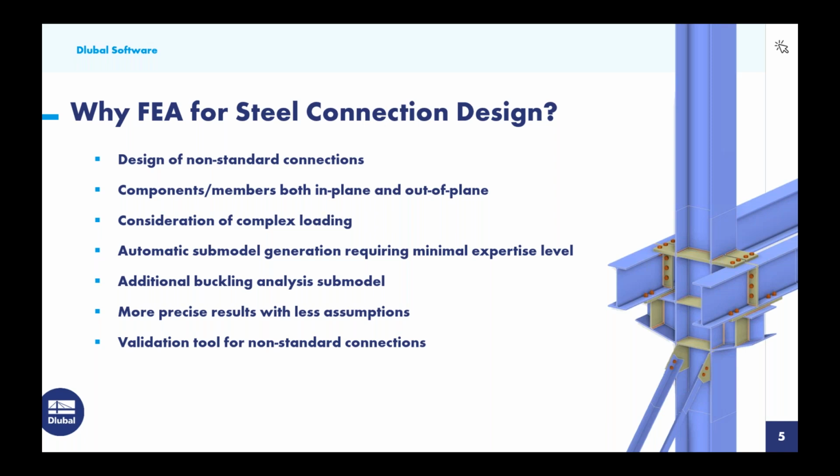They are rather complex, but if you just have a general FEA knowledge, you can go ahead and utilize this capability within the program. We also will perform the AISC design checks of these connections for our bolts, our welds, and our plates, but we will take it a step further to create a second submodel to carry out the buckling analysis. So we'll be able to view the different eigenmodes and failure buckling modes of this connection, as well as the critical load factors. So we'll see that a little bit further in the example today.